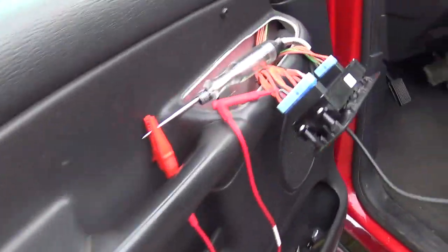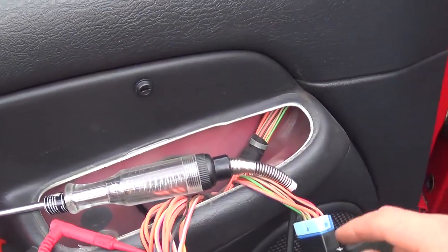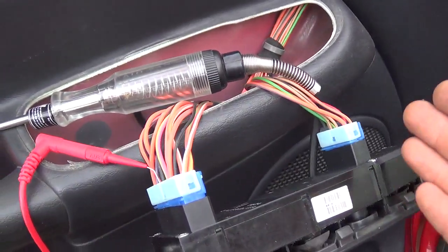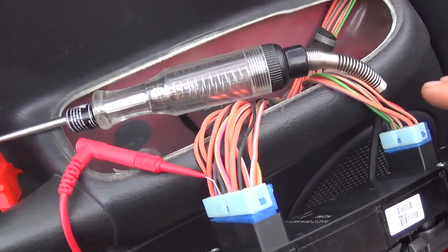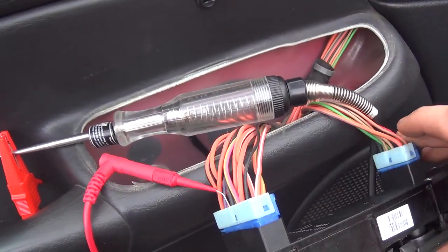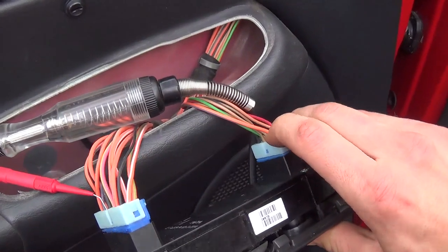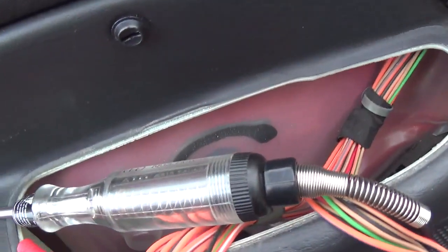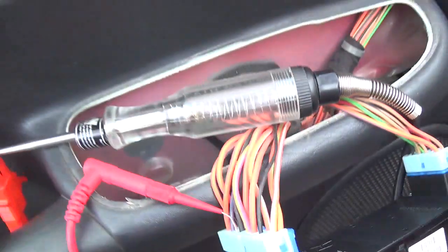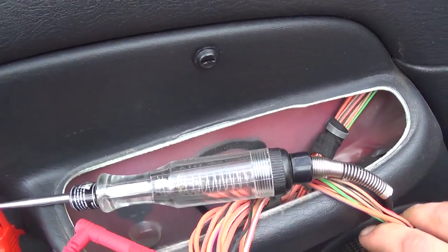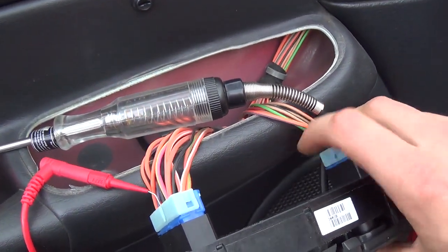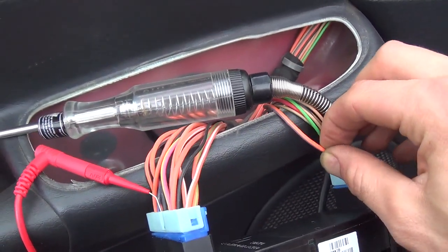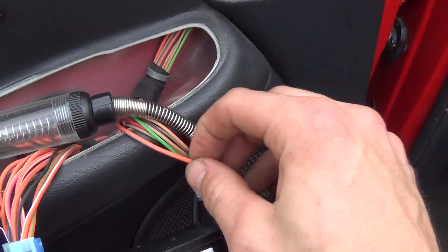That means when that motor is trying to draw amperage, something in here, the contact is just not being continuous. It's either heating up and coming apart. So, see, the light's off. We press this together. See, the problem's here. It's not here. It's something to do with this module. See, I put a little pressure on there. It's this wire right here, the orange and blue.